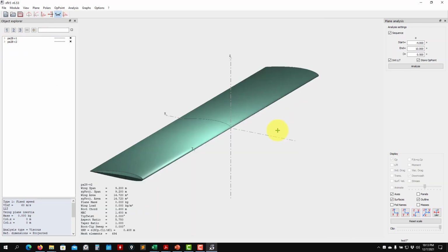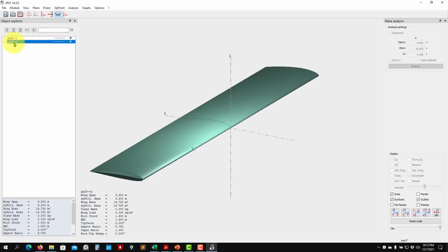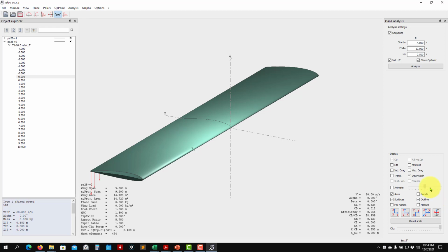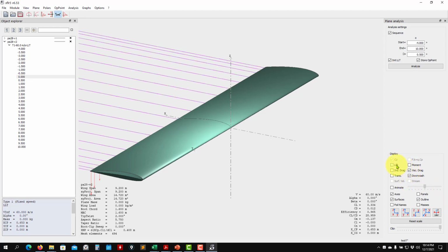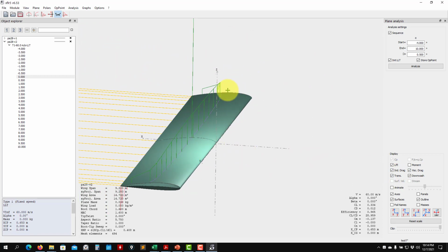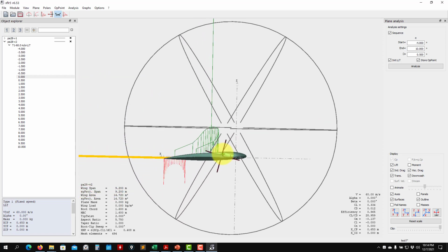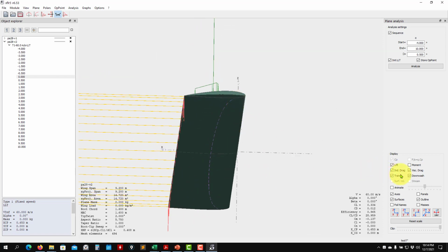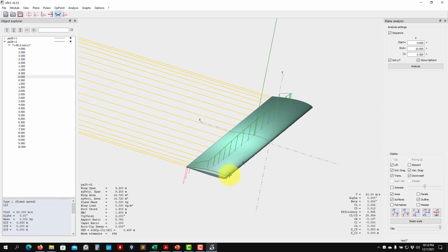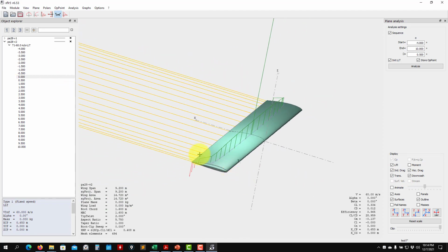Okay, so again, you can come back here and you can get access. You click there, and then you have the angles. Okay, remember that you expand and you go to 0, as you want to see all your arrows and this stuff. So this is mainly, see that also this represents the transition, when the transition happens, okay? And you have access to that information because you are running Airfoil in viscous mode, and you have all the transition location. So important things that also I want to point out.